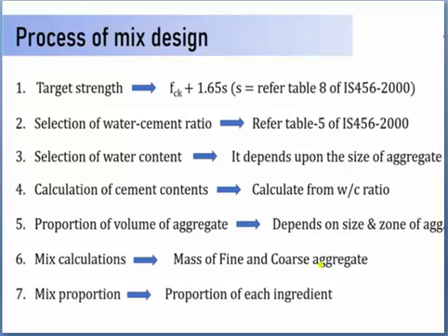So first is the target strength, the calculation of the target strength, then selection of water cement ratio, then selection of water content, then calculation of the cement content, then proportion of volume of aggregate, which will depend upon the size and zone of aggregate, then the mix calculation. In the mix calculation, we are calculating the mass of the fine and the coarse aggregate, and finally the mix proportion.